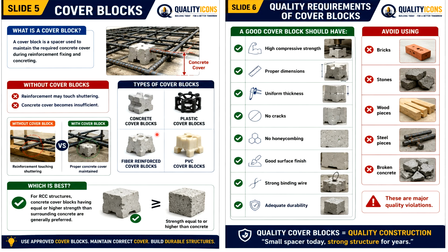Types of cover blocks. What types of cover blocks are available? Concrete cover blocks, plastic cover blocks, fiber reinforced cover blocks, PVC cover blocks. Which is the best? For RCC structures, concrete cover blocks having equal or higher strength than surrounding concrete are generally preferred. This is very important.